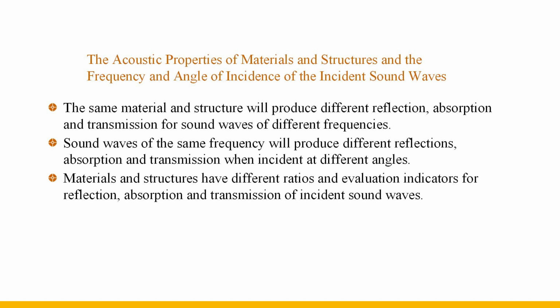According to the different incident angles, it is divided into vertical incidence sound absorption coefficient, oblique incidence sound absorption coefficient, and random incidence sound absorption coefficient. The random incidence sound absorption coefficient is also called the diffuse incidence sound absorption coefficient. The normal incidence sound absorption coefficient is measured by the standing wave tube. The random incidence sound absorption coefficient is measured by the reverberation chamber. There are few cases of vertical incidence and oblique incidence in the architectural acoustic environment, and random incidence is common.